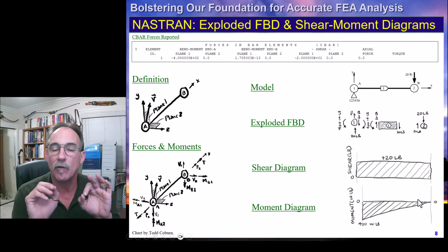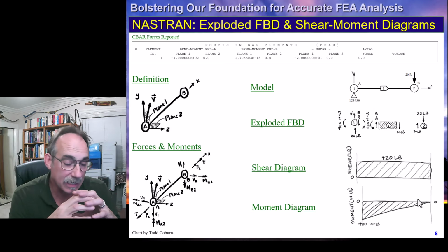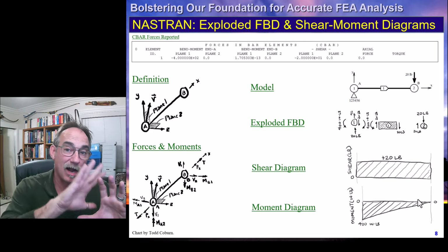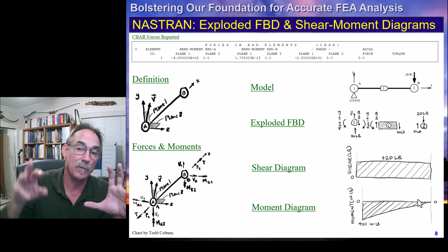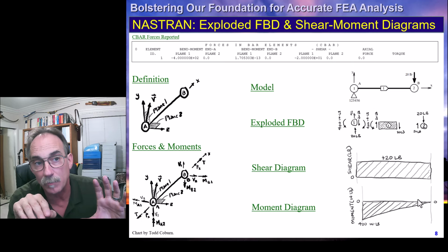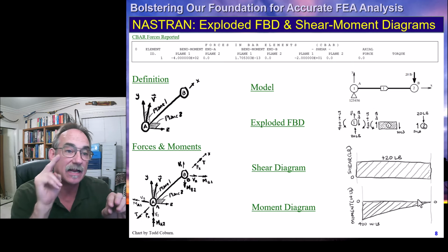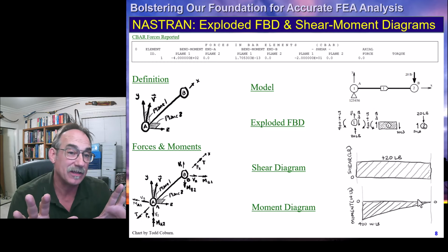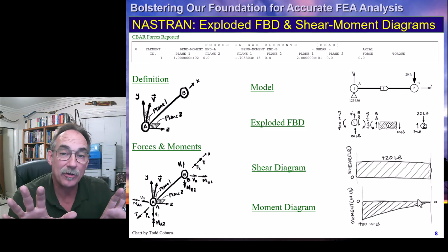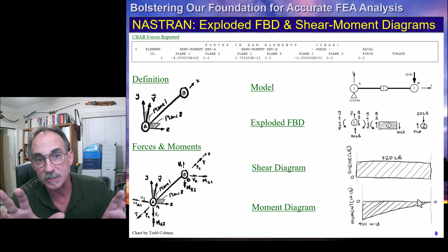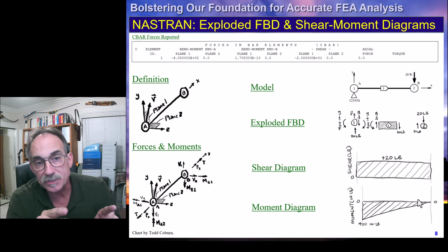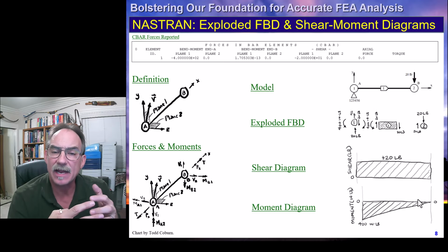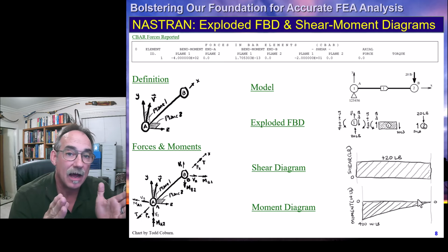This is very powerful for being able to look at a structure like a frame, a cross-sectional frame, and look at the shear and moments and axial loads on the frame and on the floor beam and struts, and quickly identify which spots are needed for additional hand analysis, and be confident that we have evaluated the critical loads and stresses for the model. We can do this by hand on a simple model, and then if we run into it and need to plot that up, we can plot it up on an element or series of elements in a bigger model.